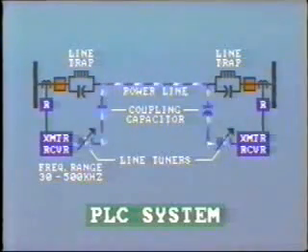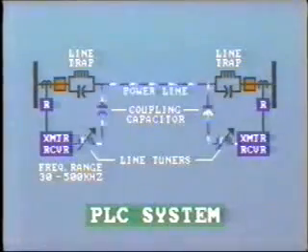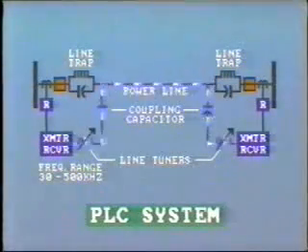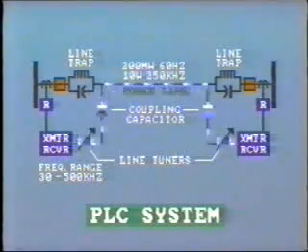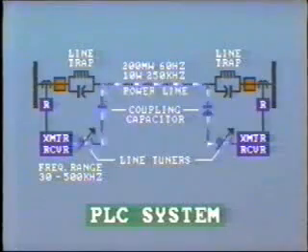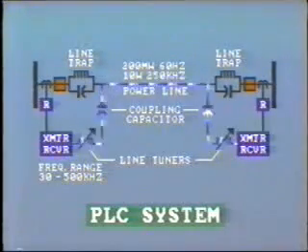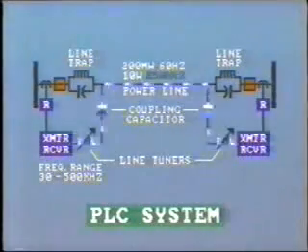The power conductor provides the metallic path for the signal. The power line, in fact, is carrying, say, 200 megawatts of power at 60 hertz and 10 watts of signal at 250 kilohertz. The first question is, how do we confine this high-frequency signal to the line itself?